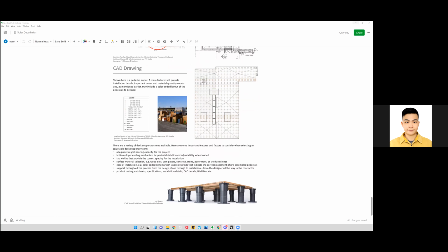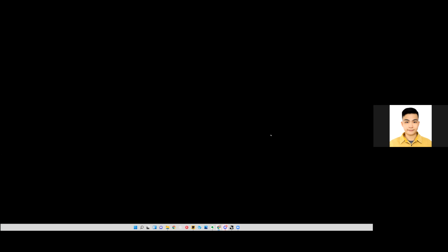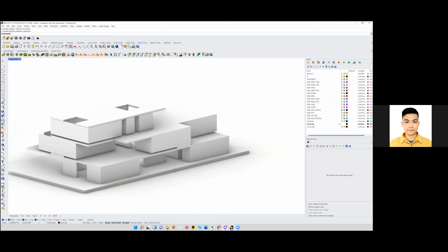Yeah, but I think the drainage point would be best placed closer to the perimeter of those wall panels, and for that we don't need lengthy drainage pipes.